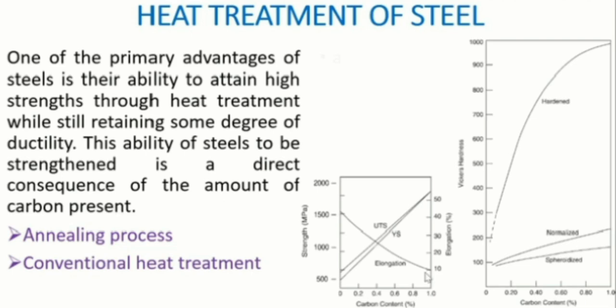So there are two things here. For steel, we should know from the background that the carbon content is important in the strength of steel. So the higher the carbon content, the higher the strength. Can we see from this diagram first by the left? The strength, you can see as the carbon content increases, the yield and ultimate strength increase. Are we together, please, class? You can see it's increasing. Can you see my mouse head?